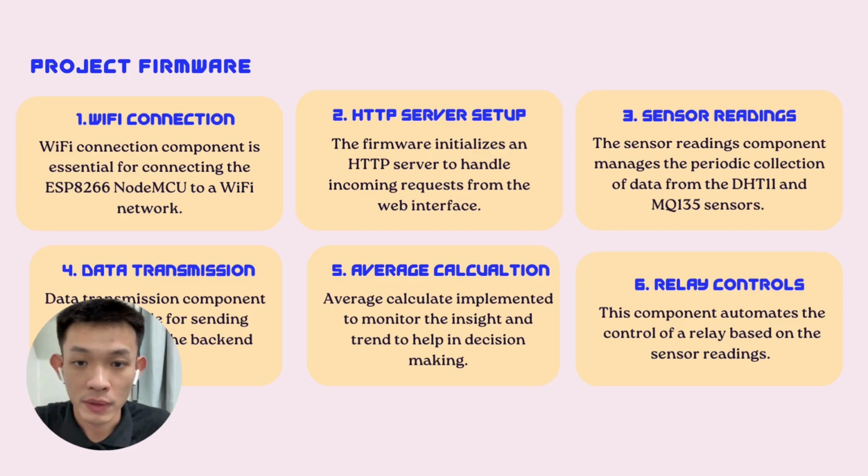My project firmware consists of 6 key components. First is the Wi-Fi connection. Connects the ESP8266 to the Wi-Fi network to enable communication with the back-end server. Second, HTTP server setup. Initialize an HTTP server to handle the web interface requests for remote interaction.